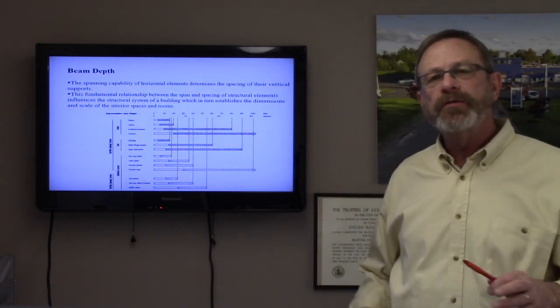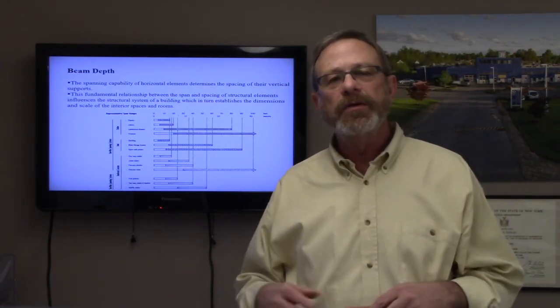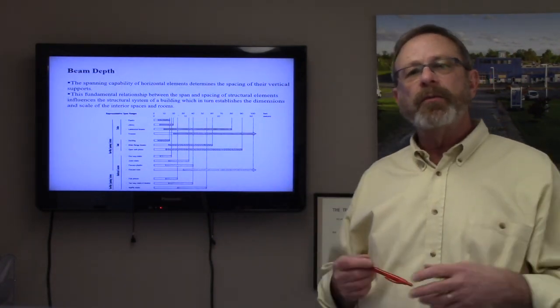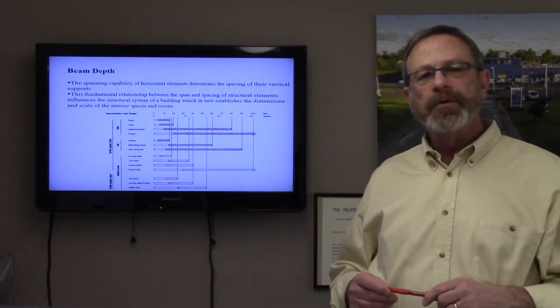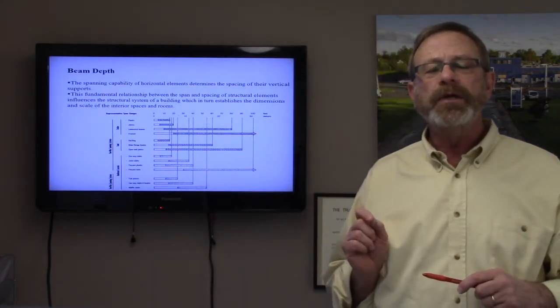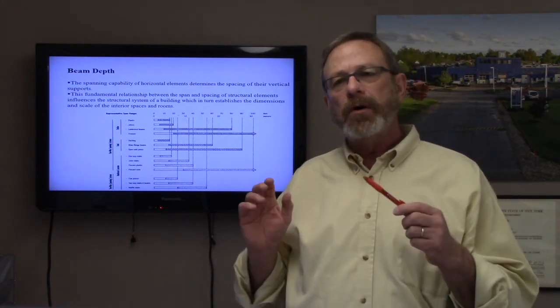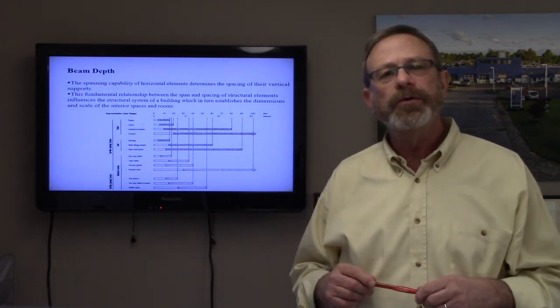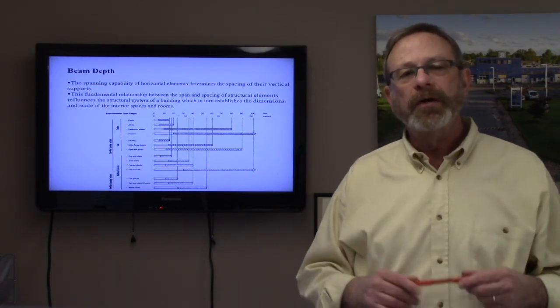So some of those equivalencies are in this chart here, where you can match joists and trusses against each other, and see what spans are available or possible with those different types of framing members. And also those are important to know because they establish the grid of your structure. The structural grid is imposed upon everything that you'll do in your design. Whether you use that grid or work against that grid, it's always going to be there.